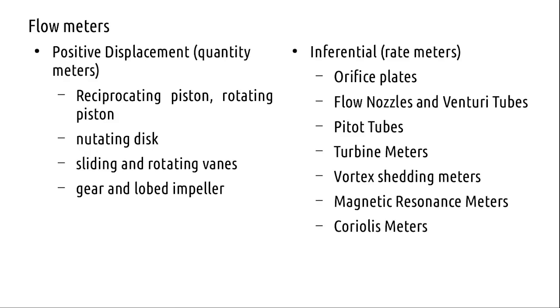How is the seepage water in a dam measured, how much water leaks out of, for instance, the Mullaperiyar Dam? There are specific types of devices, very crude but very useful measurement devices, something like a V-groove structure, which is placed in the path where the water flows, and you can measure.